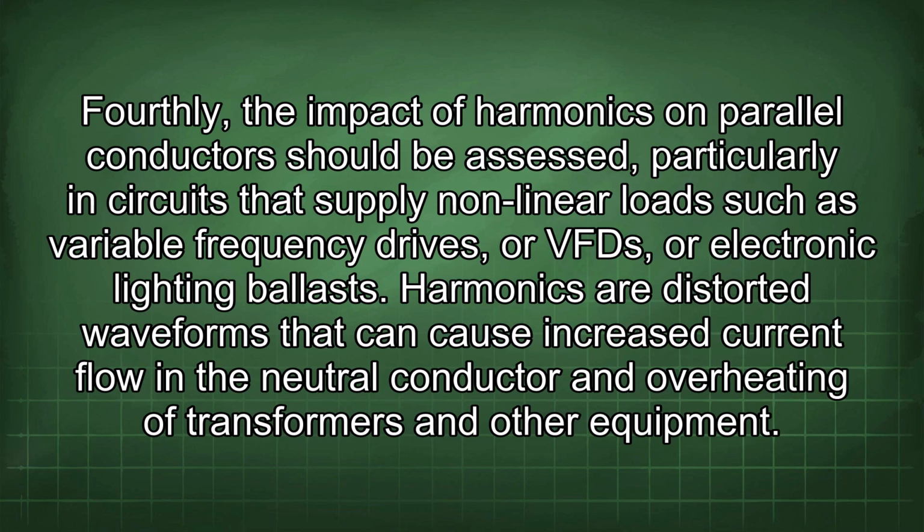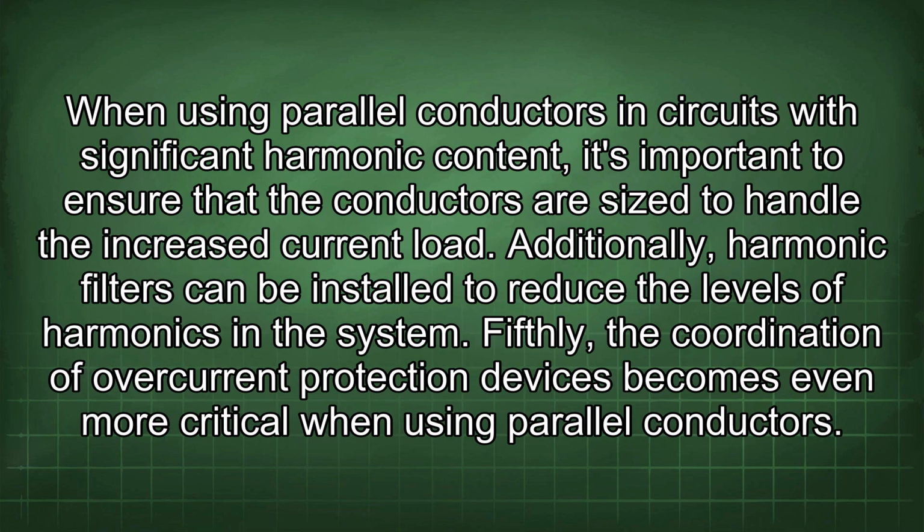Fourthly, the impact of harmonics on parallel conductors should be assessed, particularly in circuits that supply nonlinear loads such as variable frequency drives, or VFDs, or electronic lighting ballasts. Harmonics are distorted waveforms that can cause increased current flow in the neutral conductor and overheating of transformers and other equipment. When using parallel conductors in circuits with significant harmonic content, it's important to ensure that the conductors are sized to handle the increased current load. Additionally, harmonic filters can be installed to reduce the levels of harmonics in the system.